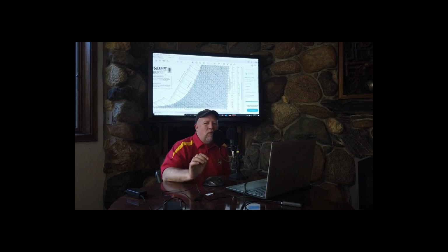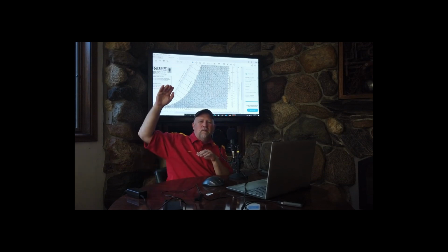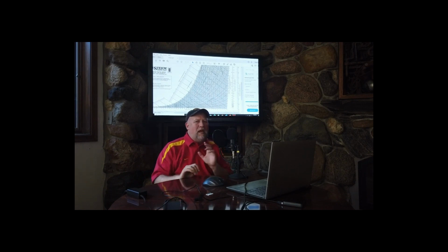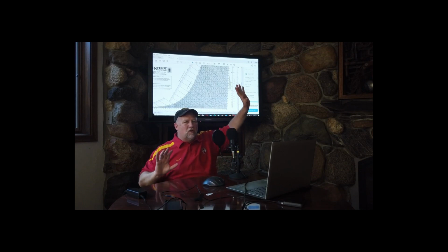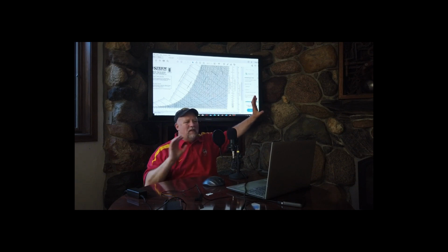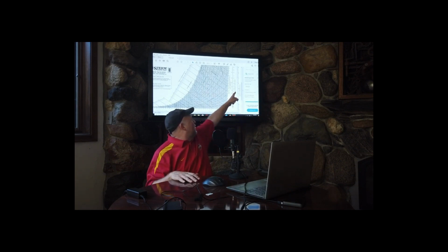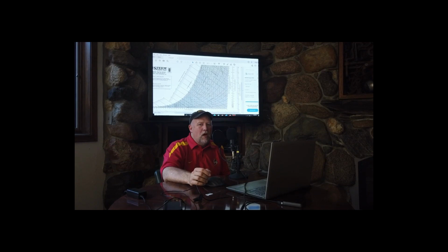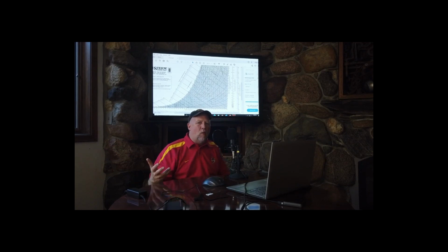The way I want you to think of this is water always runs downhill. And I don't just mean in terms of elevation. If it's in a gas form, it goes from higher concentration to lower concentration. And in a building, if a building is cool and dry compared to the hot, humid outside, water vapor will migrate from the outside to the inside simply because vapor pressure is going to force it that direction. You don't have to have wind-blown water on the surface of a building to get water inside.